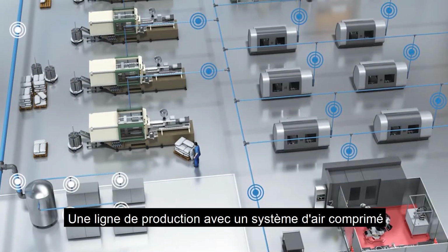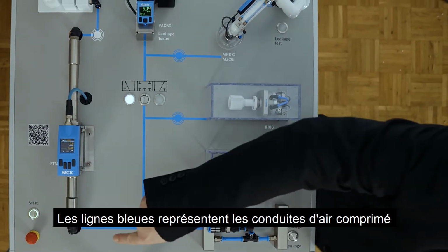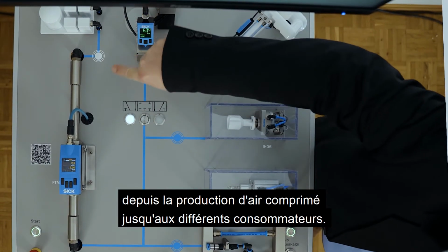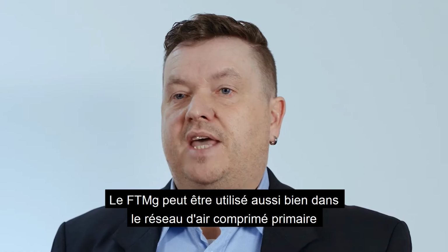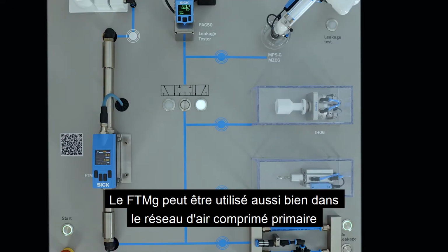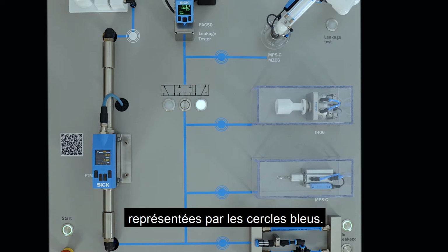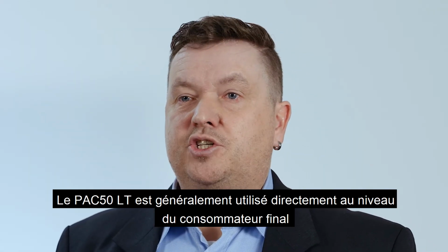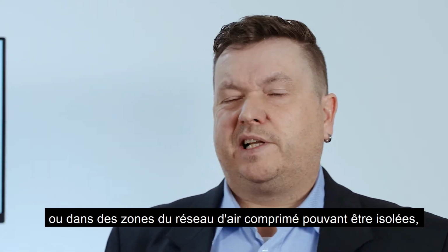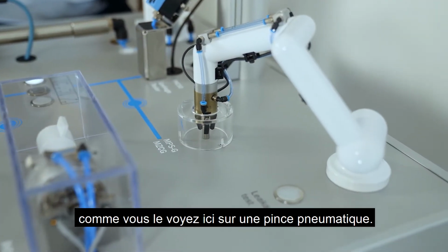A production line with a compressed air system is set up on the table as an example. The blue lines represent the compressed air lines from the compressed air generation to the individual consumers. The FTMg can be used both in the superordinate compressed air network as well as in the supply lines to the individual machines, shown by the blue circles. The PAC50 leakage tester is typically used directly at the end consumer or in separately containable areas of the compressed air network, such as you see here on a pneumatic gripper.